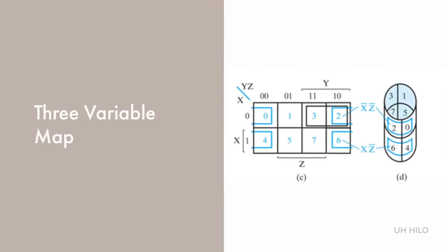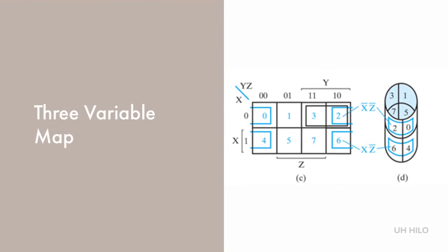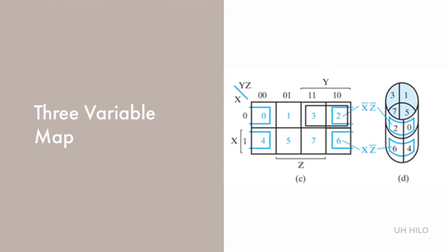A K-map in 3 variables is a rectangle divided into 8 cells. We can think of this map as lying on a cylinder, so the left and right borders share an edge. Hence, we can do things like wrap around from left to right and right to left if necessary.